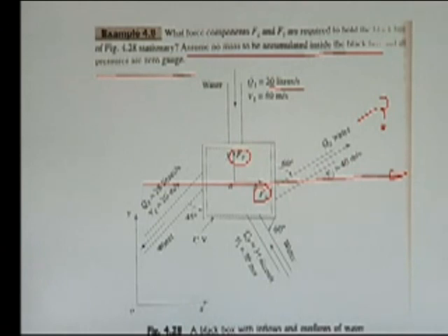Now, this Fx is equal to, flow is a steady flow, so it will be equal to dV system over dt, where the control volume term will be 0. According to Reynolds transport theorem, this is dV over dt minus B in plus B out is equal to the rate of change of the system, right.